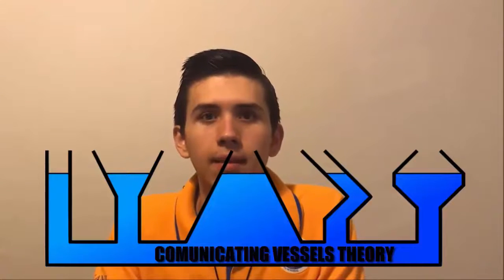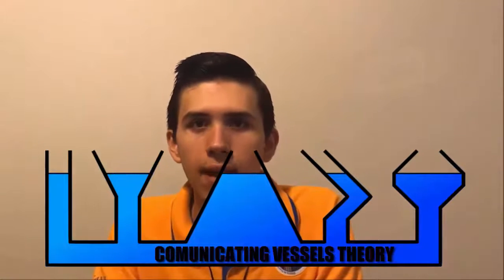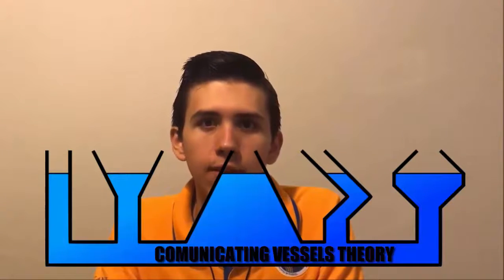This occurs because of the communicating vessels theory. If you fill one side of the vessel, then the other sides of the vessel will also fill to the same height. In this case, the tank is one part or one side of the vessel and the other sides are the homes and buildings. The water will rise until the same height of the tank with all the water. But if the place where you need the water is higher than the tank, then the water will not flow through the faucet.